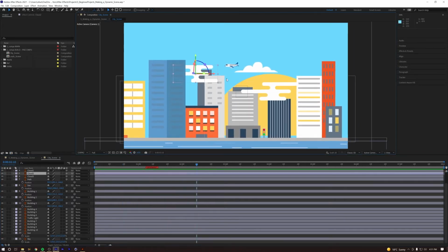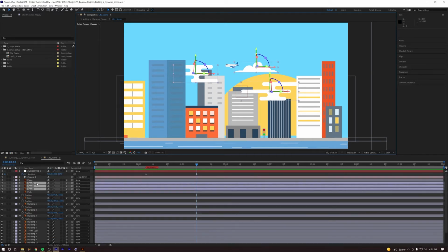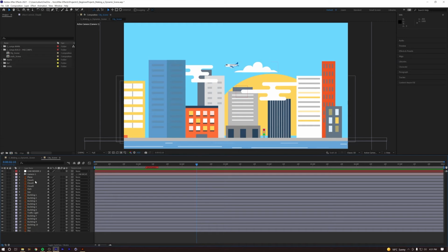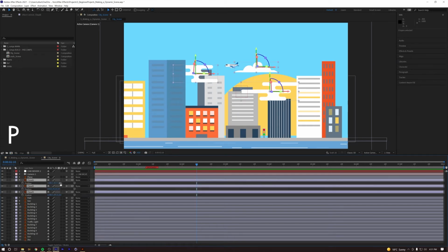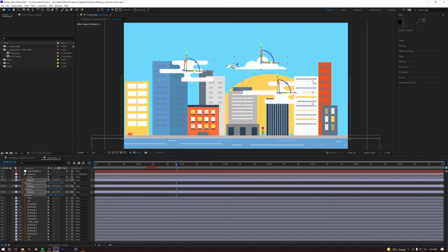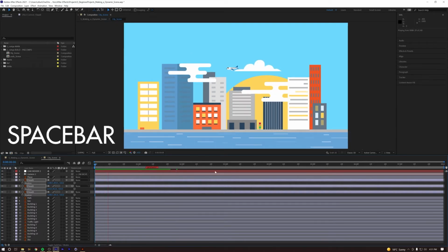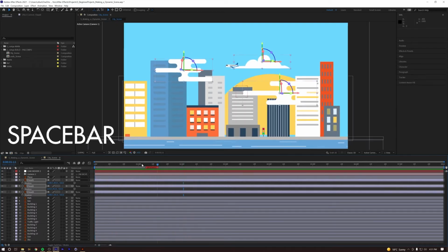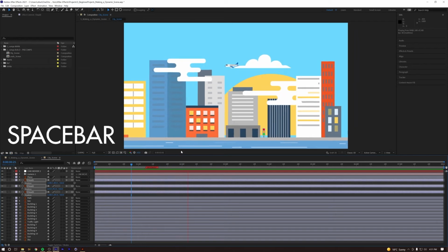The clouds are behind the buildings and that's not what I want. I want the clouds to be almost my most foreground layers, okay? If you press Command A and press U to close up everything, and click on my clouds and then press P, and then drag them really close to the camera, say around there. We can scale these later if they get a bit too big, but we can see some motion going on. I'm going to make them even closer to the camera again. So if we press play, see we're getting some 3D kind of parallax going on with these guys.